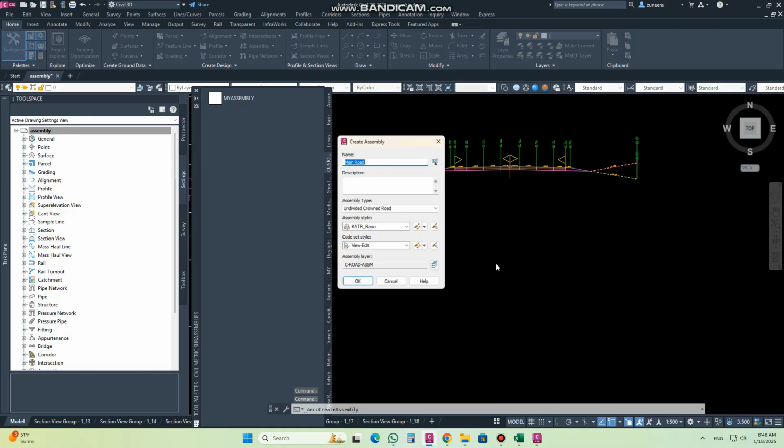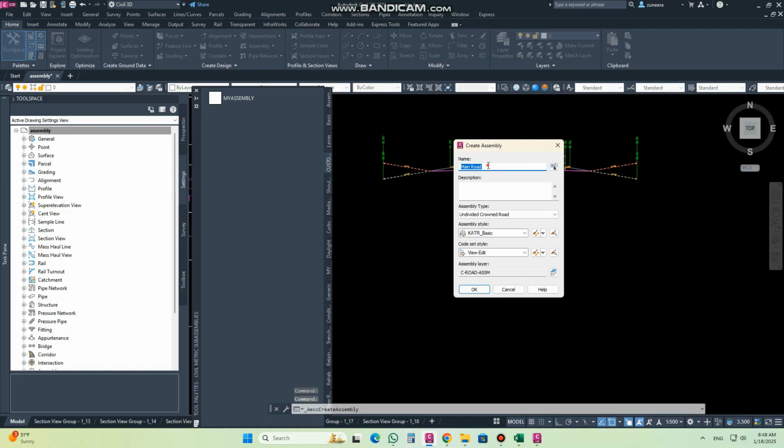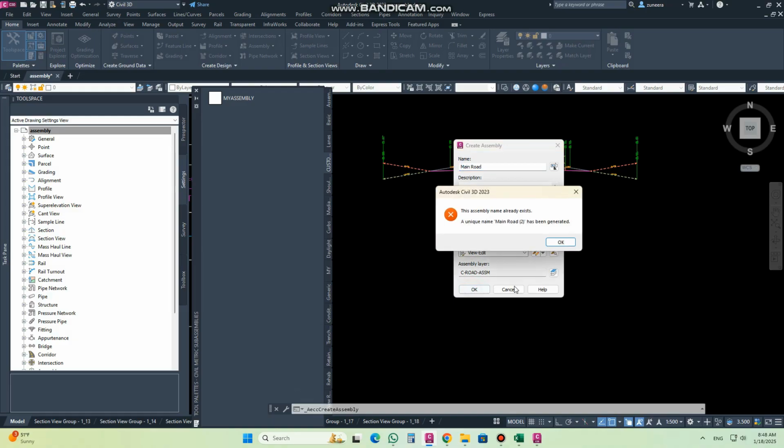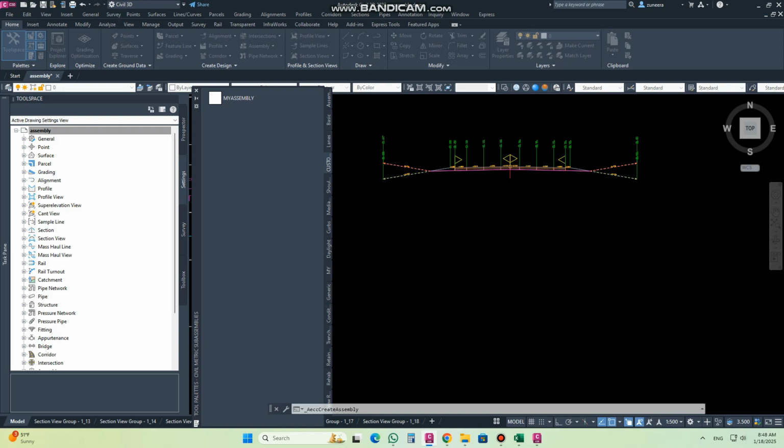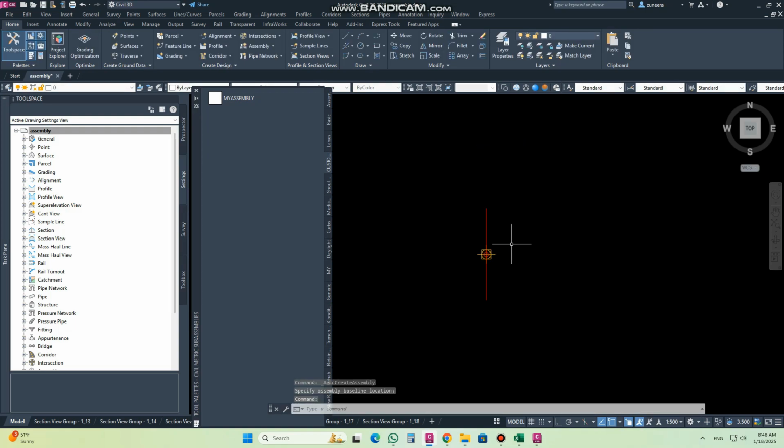Now as you can see, my subassembly appears here. The same length and slope I put here, as you can see, 3.65, and the slope. If I go to the properties of this subassembly, the same things which I put in Subassembly Composer you will find here.